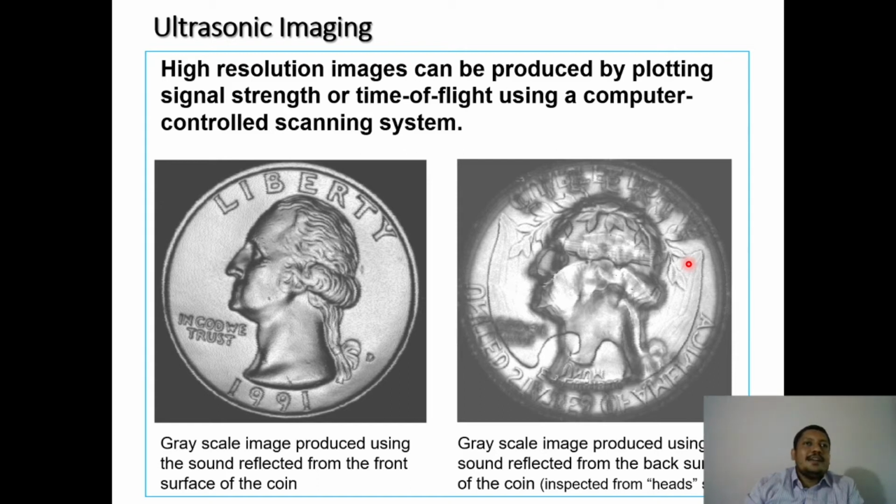Whether a defect has occurred or not, you have to test it. The common testing procedure is the NDT process. If a defect has occurred, you have to see whether it is an acceptable flaw or not. If it is acceptable, don't worry, you can continue as it is. Otherwise, you have to go for repair.